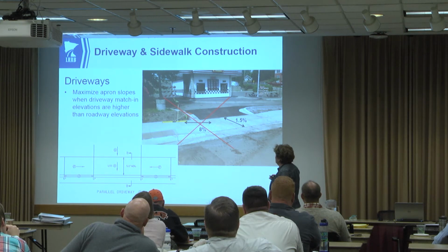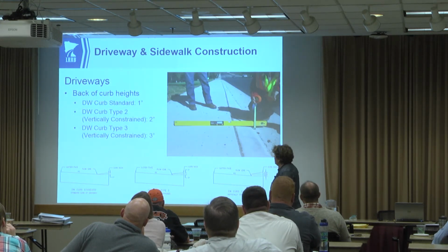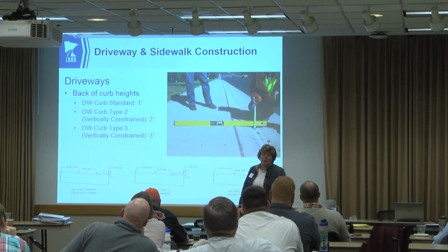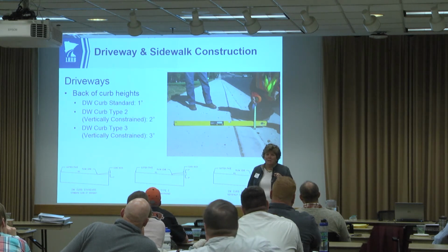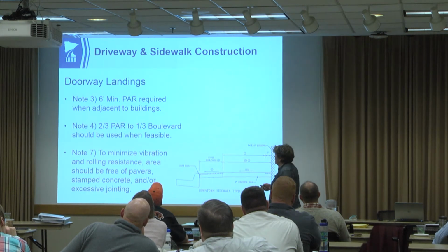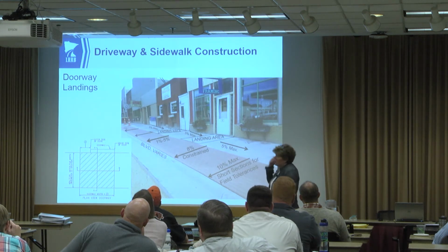Make sure that this kind of situation doesn't happen, that this ramp is not there. We don't want ramps into our driveways, that longitudinal grade does not exceed 5%. There are some details in the standard plan for working with back of curb height. So if you're trying to squeeze an inch out of a driveway, which sometimes could happen, you can use a different curb detail.